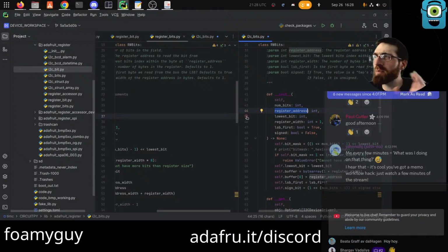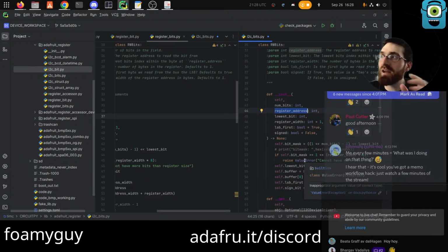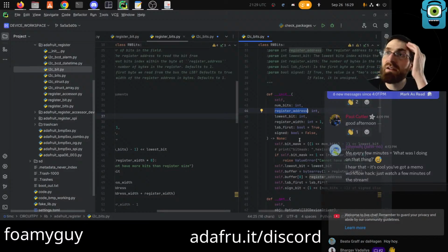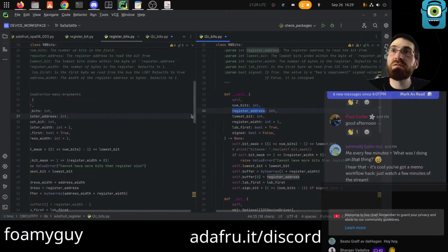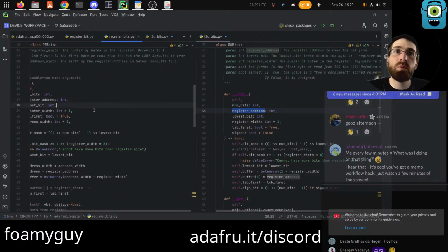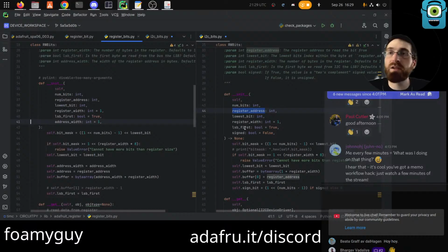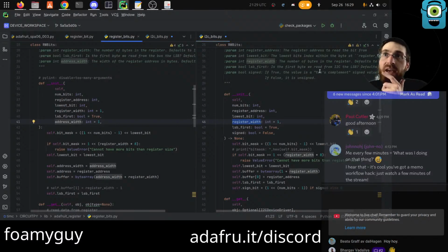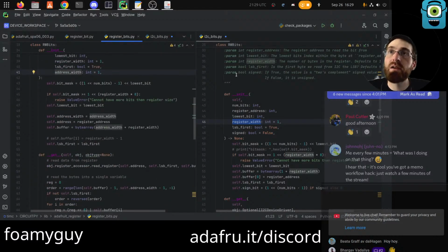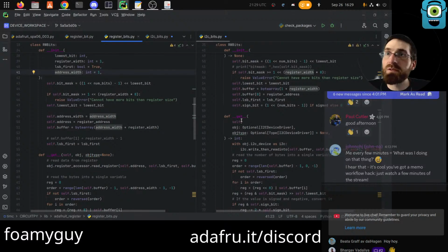I think there are a couple of weirdo I2C devices that maybe use a 10-bit address. And for SPI, if I understand correctly, it's not standardized. You could have an address of 1 byte, 2 bytes, or 3 bytes, as many as the device wants, depending on how many registers it has. So this new refactor is attempting to support that multi-byte address width. We always supported multi-byte registers, of course, but this is specifically the address. And I accidentally added it here without meaning to. Long story short.